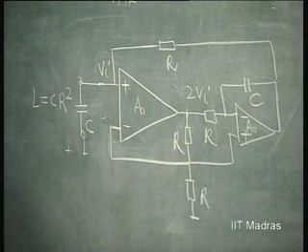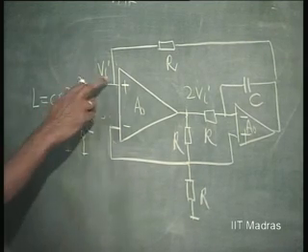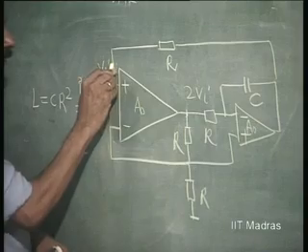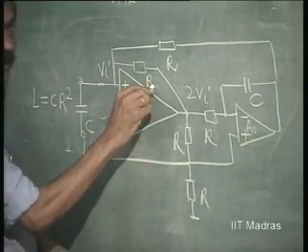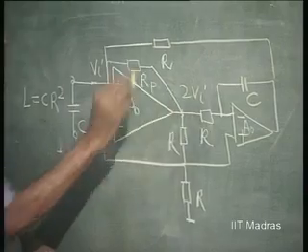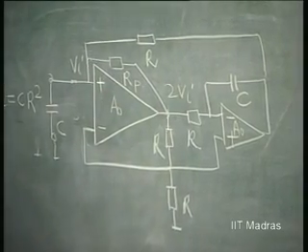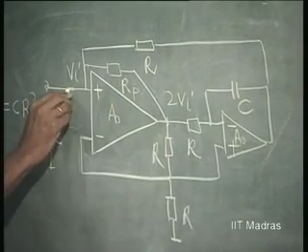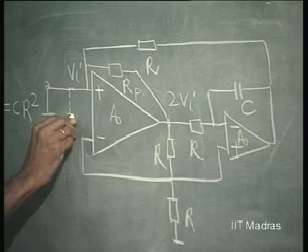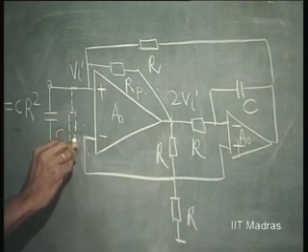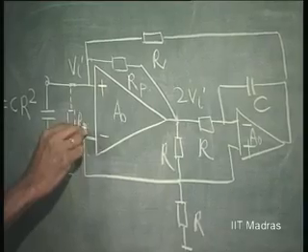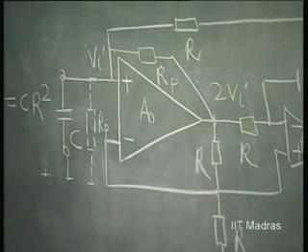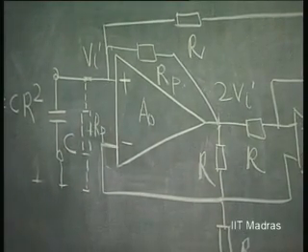So, how do I now create a negative resistance? It is very simple now, from Vi to Vi. So, I put a resistance here which is Rp. That will compensate for the so called loss component which is already existing, whose magnitude is equal to Rp. So, this circuit will invariably burst into oscillation.